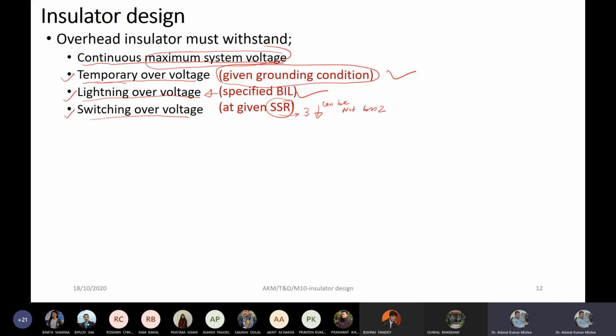And once we reduce this 3 by the switching surge ratio below 3, we should also reduce the temporary overvoltage. Just reducing this single one is not advantageous. I have mentioned insulation coordination to you. In fact, insulation coordination is taught in two terms: one is equipment to equipment, and another is from one type of voltage to another type. So this coordinating is also insulation coordination.